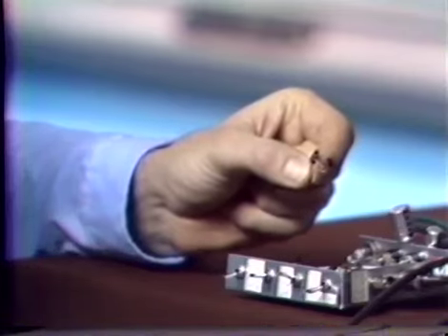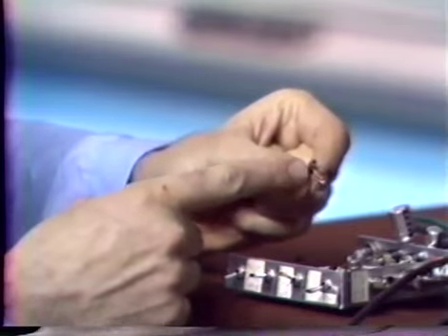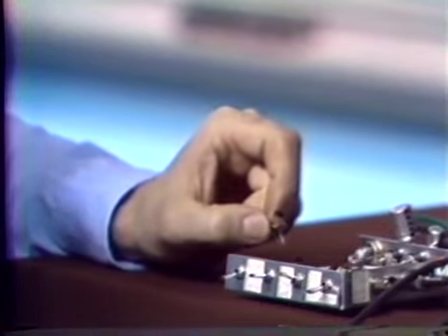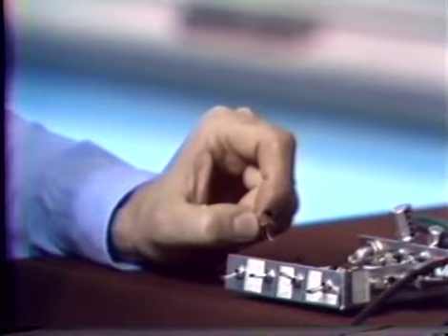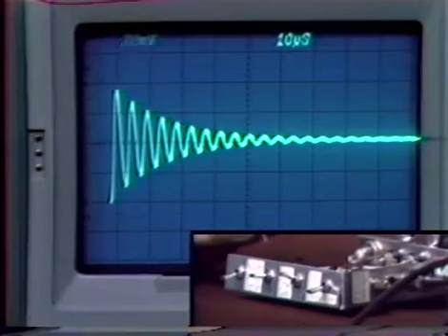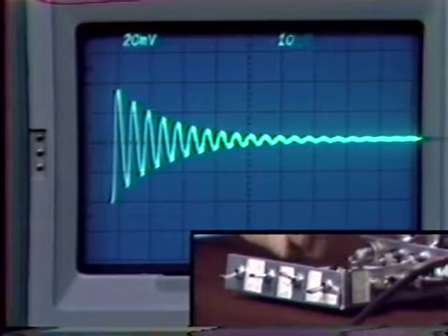But starting out, we simply have the series resistor-capacitor combination that I mentioned. And what I'd like to do is look back at the oscilloscope trace and recall that the settling time with 1/s compensation is in excess of 100 microseconds. And now let's go to the compensation that includes a zero.